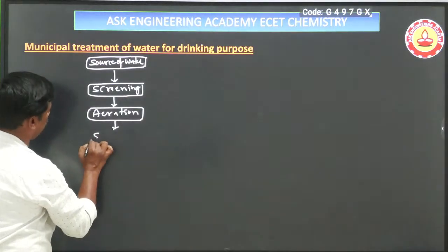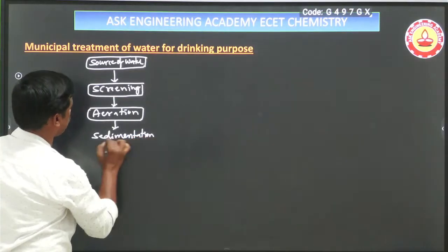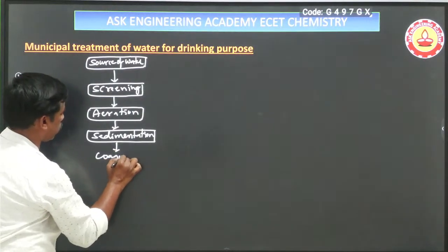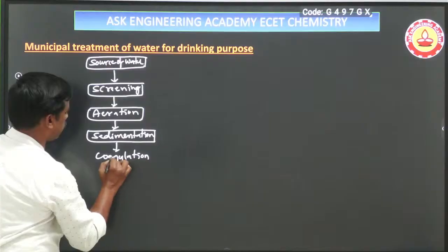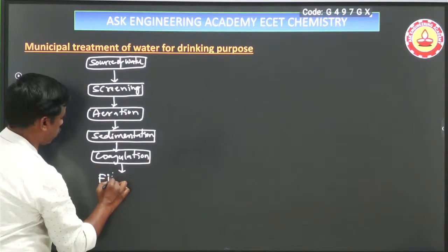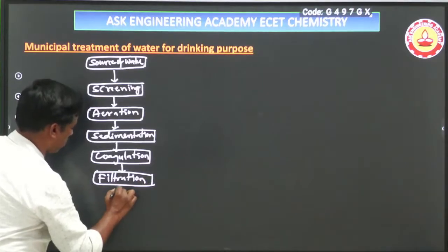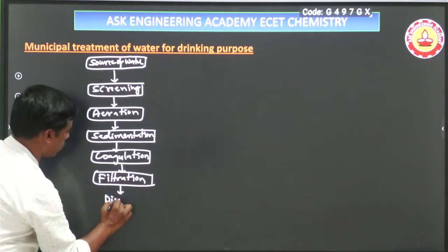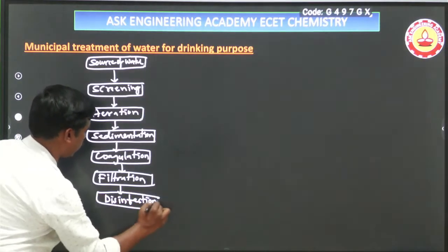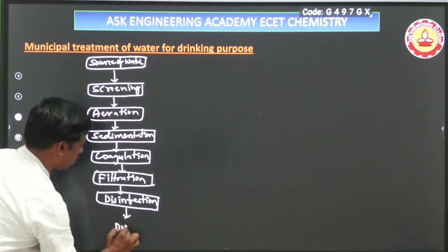After the aeration, sedimentation, next coagulation, then filtration, disinfection. After disinfection we get potable water or drinking water.